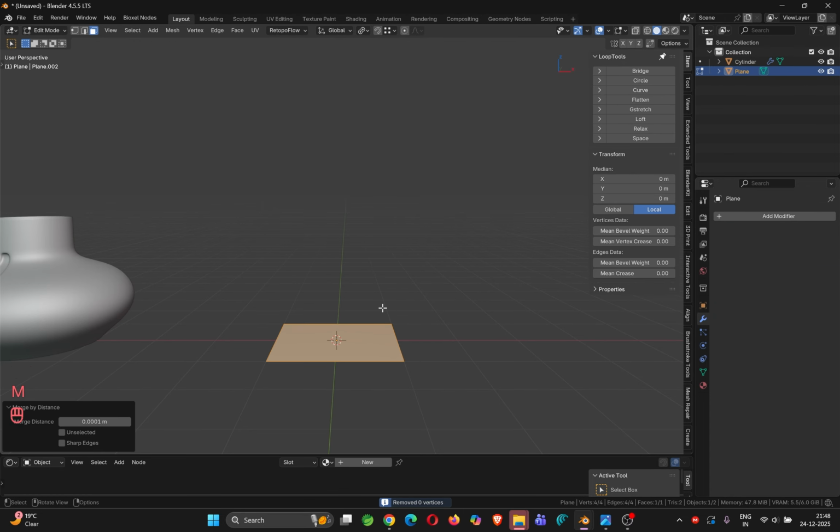Now if you want to create a circular shape out of it, Blender comes with a very nice modifier called the screw modifier. So you can just grab it from here, screw, and in my earlier tutorial on modeling a screw, I showed you that if you enable only the screw modifier, the face normal is not correct. You can verify that. See, the face normals are not correct. So what you need to do is go to normal calculation.